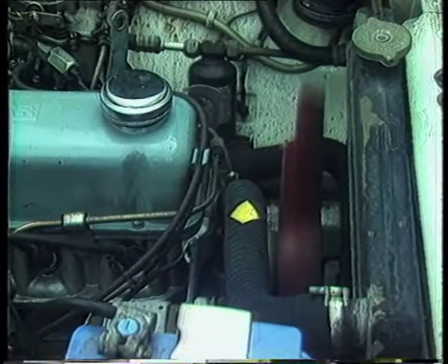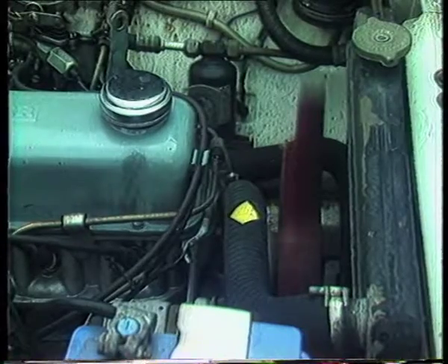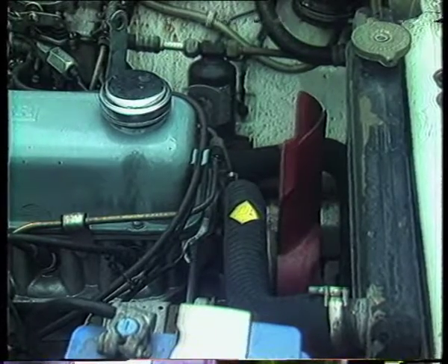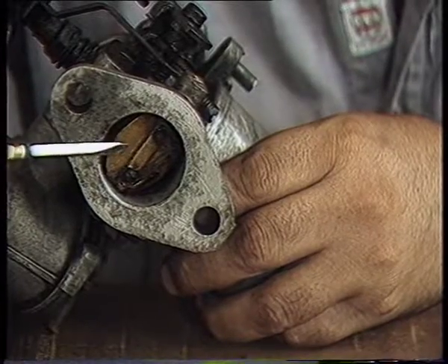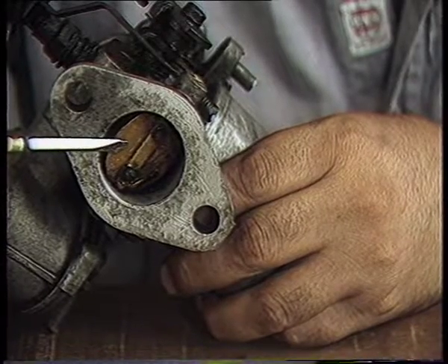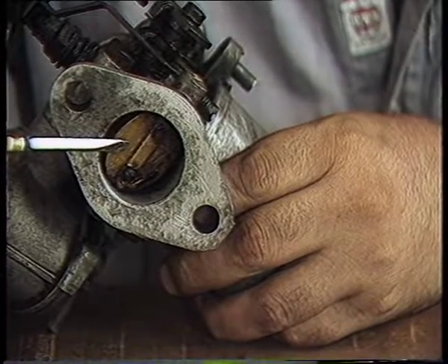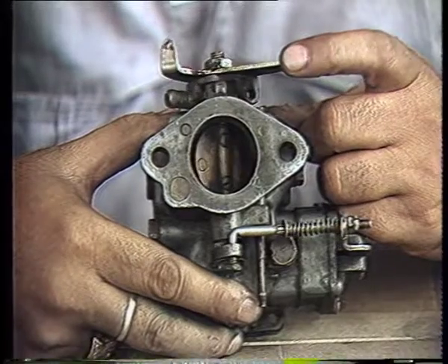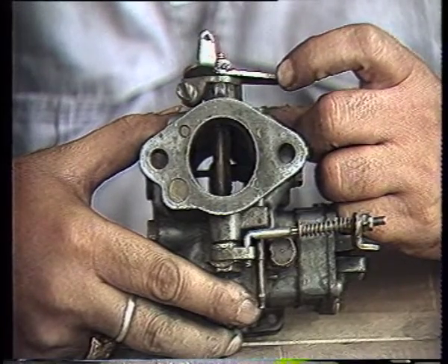Conversely, it may happen that the engine fires when cold, but will not continue running. In such cases, either the strangler flap, that is the choke, is jammed or is not opening to the required amount when the engine fires. There could be another situation when the engine does not idle. In this case, assuming that the fault is not in the engine or ignition system, the fault has to be in the fuel system.